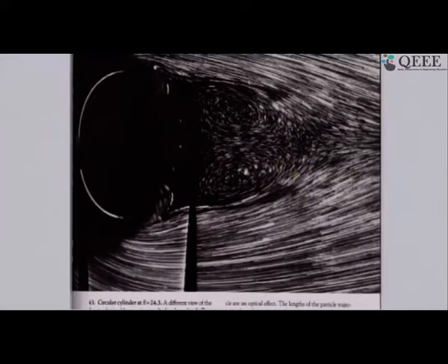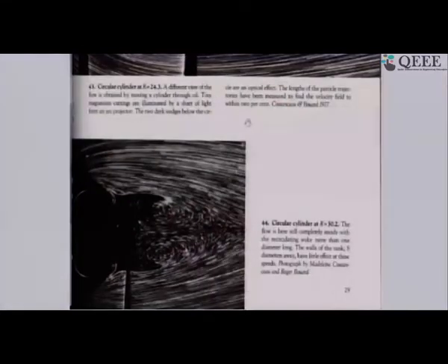Again, the same thing we see here, that you put in the particle and look at the streak lines that happen, and this is what you get. Here you can see that this is moving like that, and the separation point has now come way up over here in the cylinder. It is slowly getting somewhere over there, and it is still a laminar flow everywhere. So you still have an attached wake, and this continues and begins to approach a limit at about, say, 30.